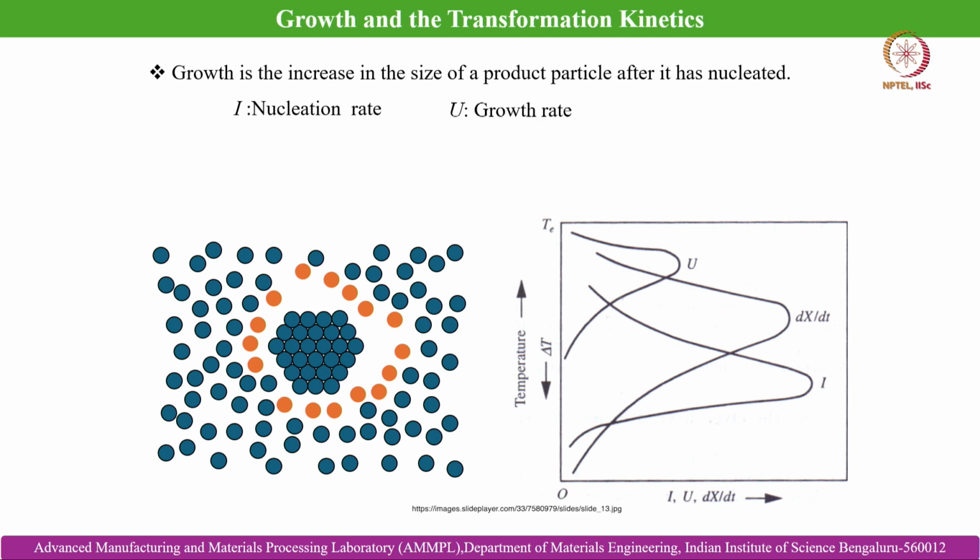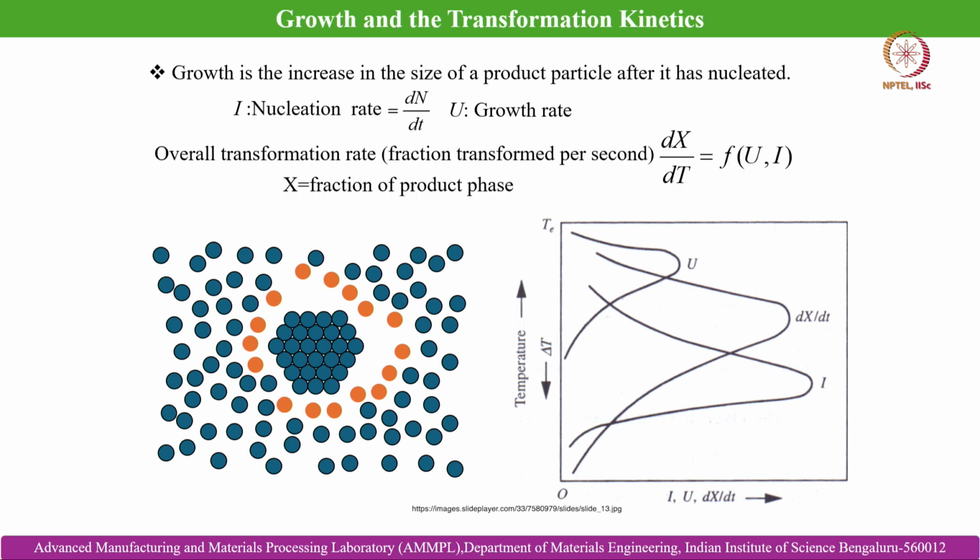With this, now I will introduce the concept of nucleation rate and growth rate. Please recall that earlier I said the solidification driving force is basically the undercooling, that is the lesser temperature as the temperature drops from the equilibrium fusion temperature Tf. You can see here, this is the equilibrium melting or fusion temperature Te. As we go down from here, the delta T value is increasing.